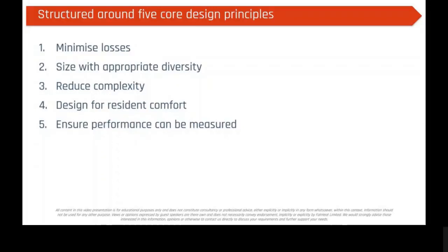We're going to define the performance in terms of key performance indicators on losses, flow temperature, meter read, stability. But if we define a metric that we want to be linked to performance, we have to be able to measure it. And that goes back to the metering strategy we put in place, the data we can extract from the system, where those heat meters are located, how frequent the data can be pulled. And so there's also a lot in the document around how do we specify a monitoring system that we can actually monitor the performance and measure it.